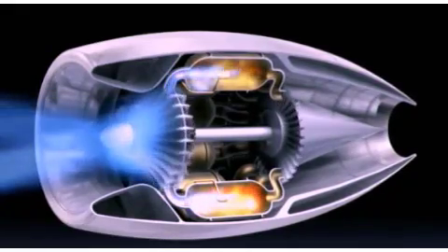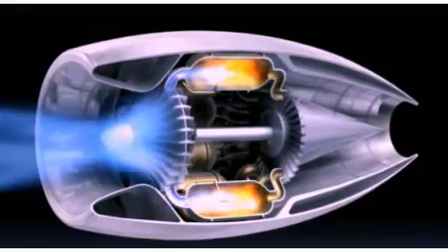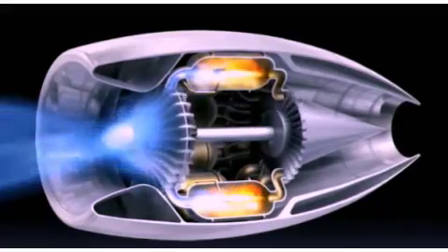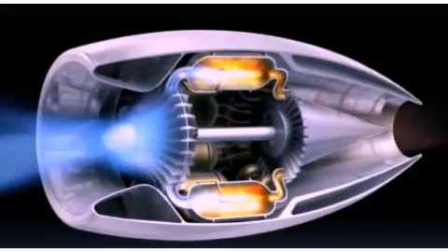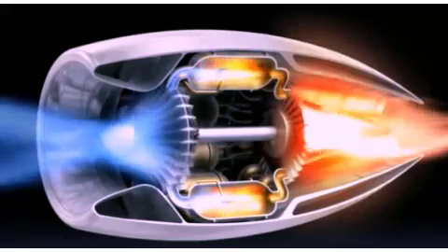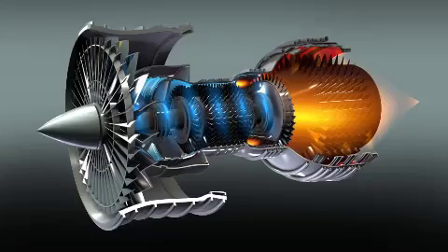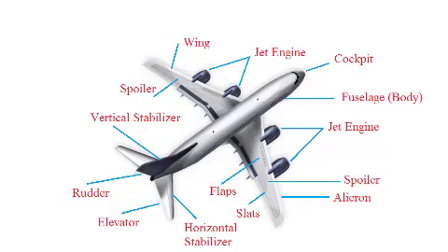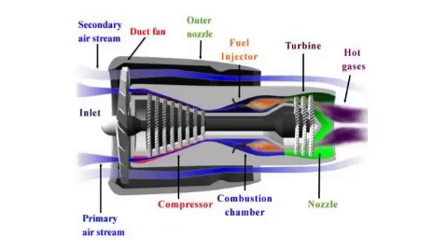Multiple nozzles inject fuel into the air, and an igniter, similar to a spark plug, causes the air to catch fire. The fuel burns with oxygen present in compressed air, producing hot expanding gases. These gases are passed through the turbines, which causes the blades to rotate. This turning of the turbine also rotates the shaft to which it is fixed. The same shaft in turn rotates the compressor.